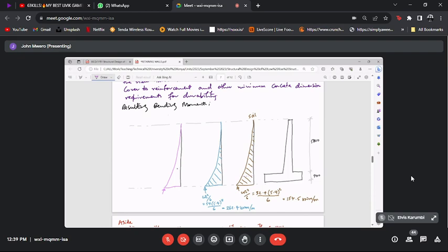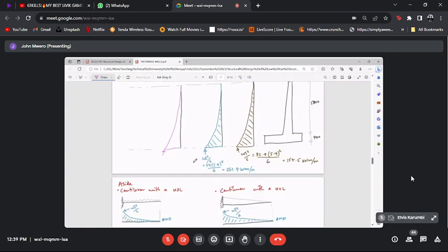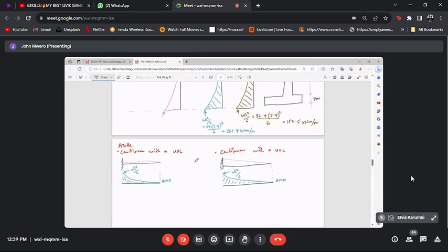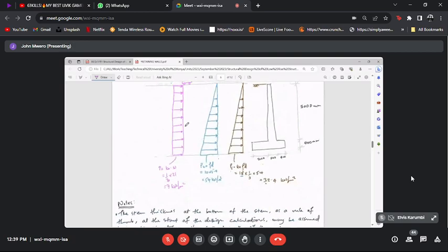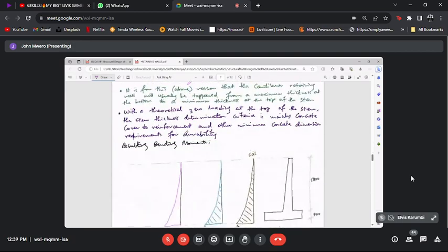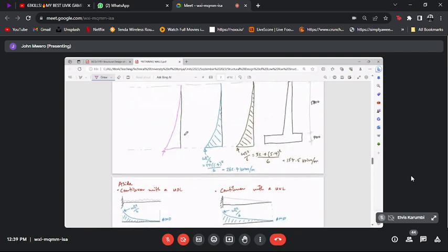Whether you want to work with the exact value where the wall is likely to fail, or you want to be a bit generous, again, it will be your call if you were to do this design. So now for this one, because it's a uniformly distributed load, we will work with WL squared over 2. Okay, so the moment here will be WL squared over 2.